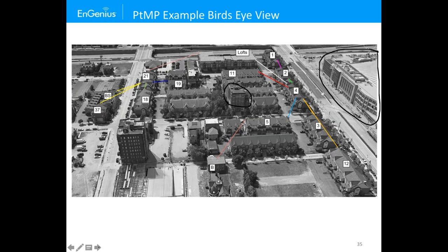With stadiums, what normally happens is that if the roof opens and they have some football games and some blimps flying overhead, the blimps have to have navigation radios that operate in 5 gigahertz. So when you deploy this, it may not have any DFS events, but when you have the event going on and that blimp is introduced, then you may have DFS events and your links will possibly go down. That's one thing to take into consideration.